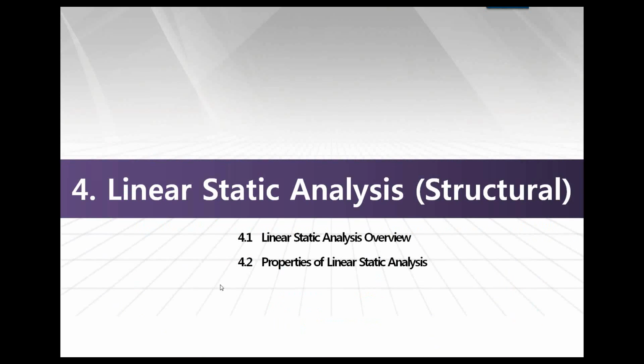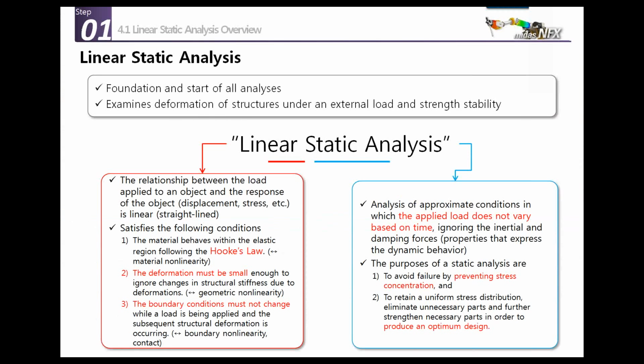So you see the shape is quite different between the two models. Now finally, let's talk about linear static analysis. Linear static is the most used because it is really the foundation and the start of all analysis. It examines the deformation of the structure under an external load, and it helps you get the strength and stability.